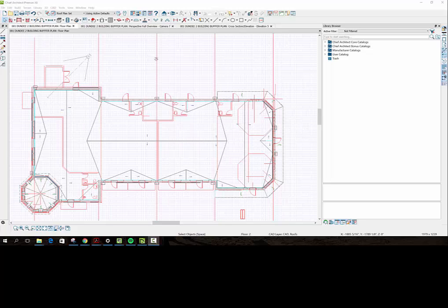Okay, we've made a few adjustments. Just shorten that up a little bit. Instead of going to the peak, we just want to build a little bit of an overframe, as that is just coming down the parapet wall, and then we direct it around the horn there. That's the low spot. So we will drop these trusses a hair lower than this in order to make sure that water gets around the horn there. Same thing on this one. So these trusses will be dropped, even just 3 inches lower, and it'll give us the pitch to go down in there.